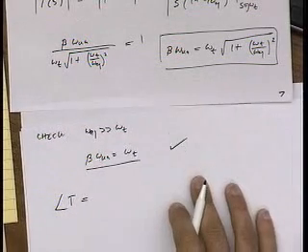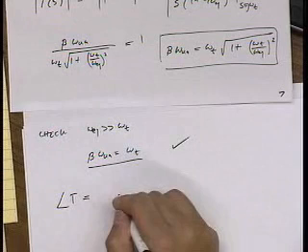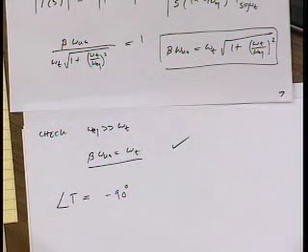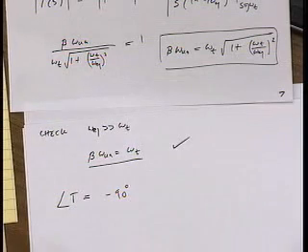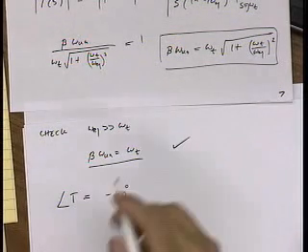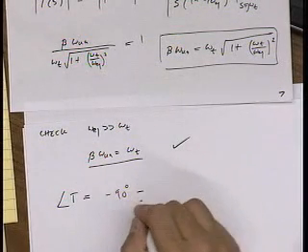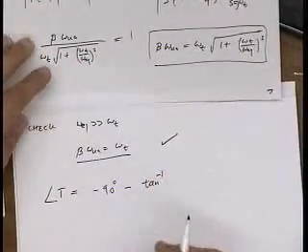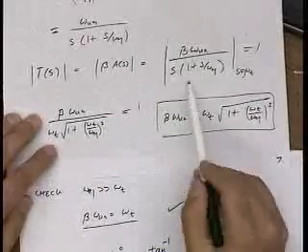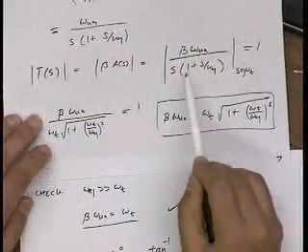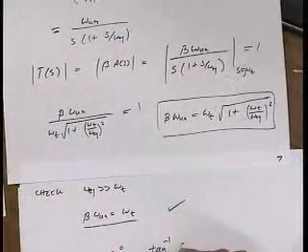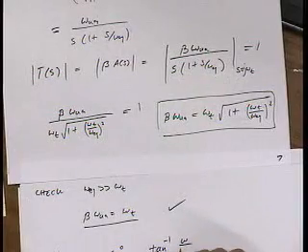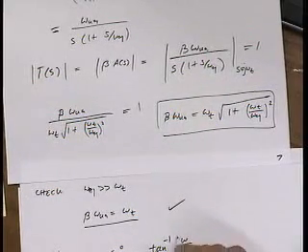So the phase of our loop gain is going to be 90 degrees from our first pole, right? Again, it's a dominant pole, so maybe it's 89 degrees, but who cares? For all practical purposes, 90 degrees. And then the effect of the second pole, so if I look at this equation, this is the 90 degree term, and then this is the effect of the second pole, is just going to be inverse tangent of omega over omega equivalent pole.